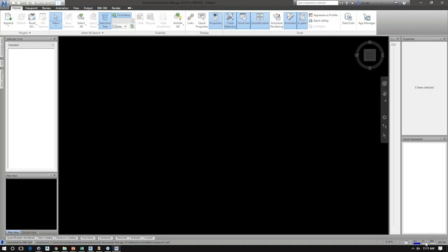With that introduction, the last thing I'll mention is that there are a couple of items on the lower right-hand side that people ask about quite often when I'm doing a training class. These icons here represent the sheet browser if you're working in a project file that has attached sheets via PDF or some other format like DWF. And then these three icons on the lower right represent processes that Navisworks is undergoing as you're manipulating the project. The pencil icon indicates writing to the hard drive, redrawing on the screen. The cylinder shape indicates writing to the hard drive, and because you can open up a Navisworks project from the cloud, this represents your network connectivity. So at any time, if you see those flashing, you'll know that information is being written to and from those sources.